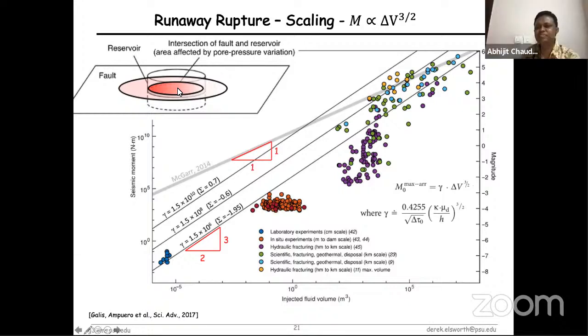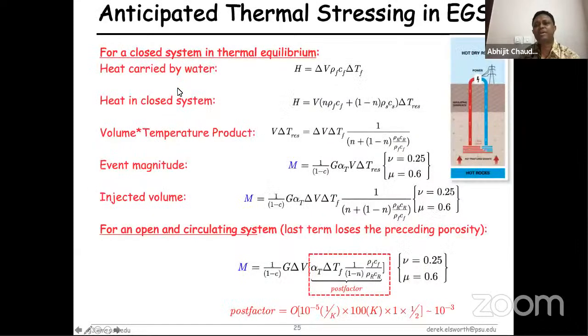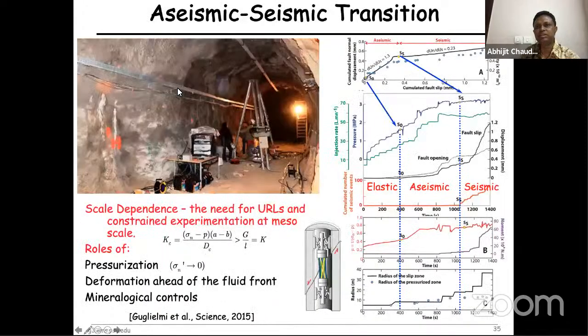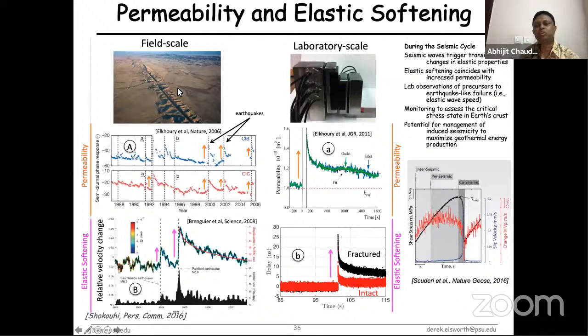Okay. And regarding the permeability change with time or with displacement or slip, it is very interesting to see that I was earlier thinking that permeability would increase over time, but your result shows permeability decreases with time. So is it the case that when the slip happens, the surface becomes smooth, the interface between fracture and the rock matrix becomes smooth, and the aperture decreases?